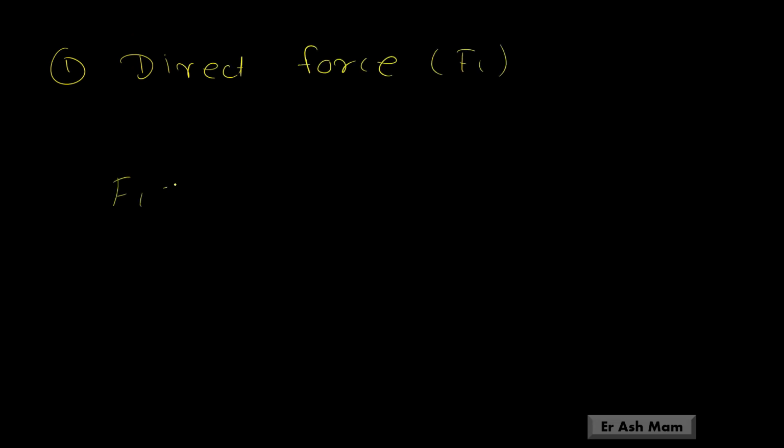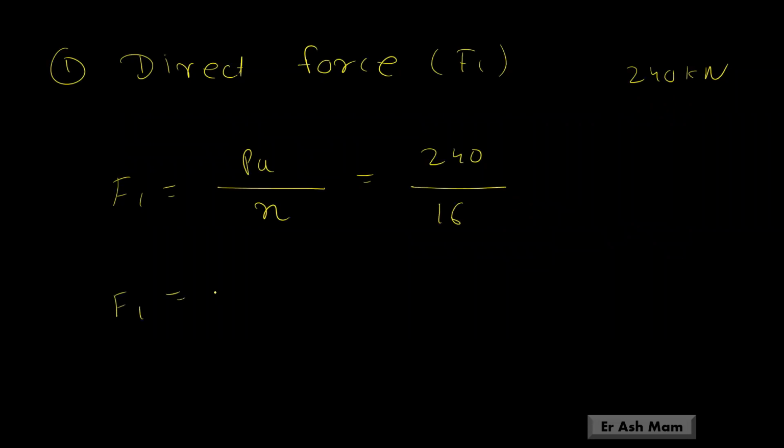Direct force F1. We know that the load is 240 kilonewton and the number of bolts is 16. Therefore, direct force will be 15 kilonewton. It means one bolt will share 15 kilonewton load.